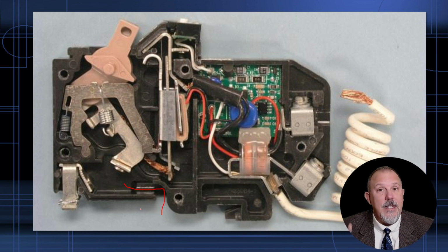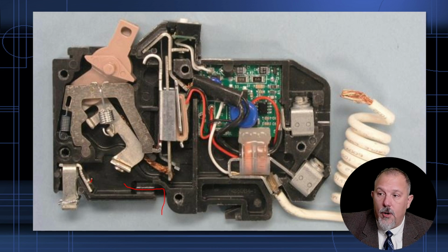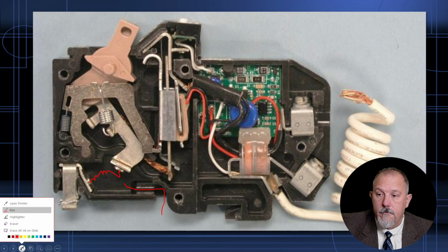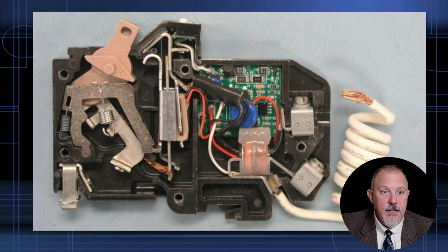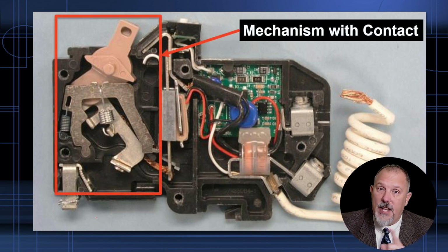But I do need an area for the gases to escape when we interrupt the arc, because you will draw an arc between that contact point and this contact point. So that's where the business happens. This is where all the activity goes down when we are opening the circuit breaker.